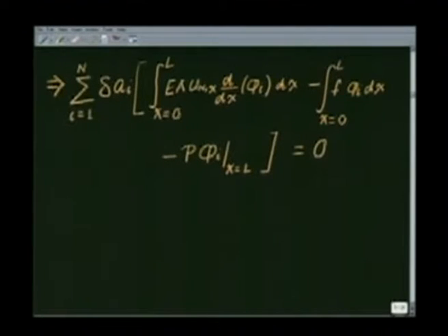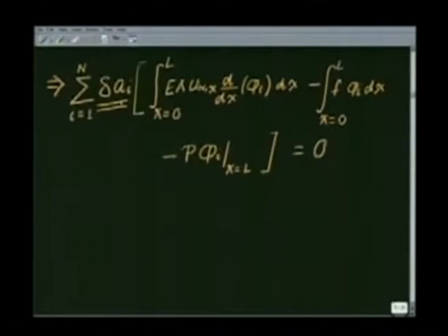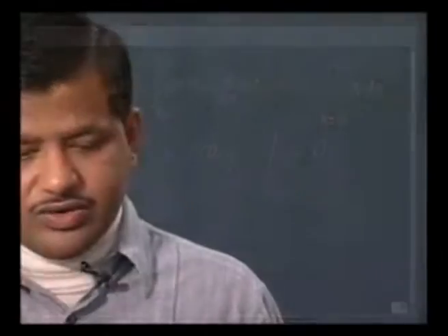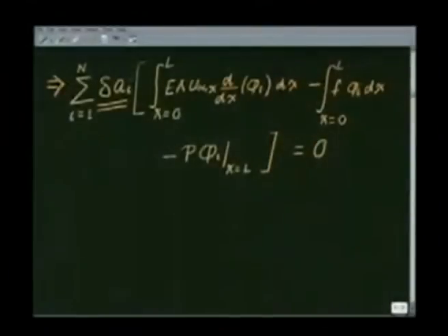Next, how do we get the equations using which we can determine the unknown coefficients a_i? That is our goal. Look at this variation of a_i. This is something that is under our control. The variation is in a way an abstract virtual displacement that I am giving to the structure, which is already in equilibrium. So I can choose what kind of variation I give. In a way, what I am saying is that we can vary each of these a_i's independently, i.e. these are independent coefficients.